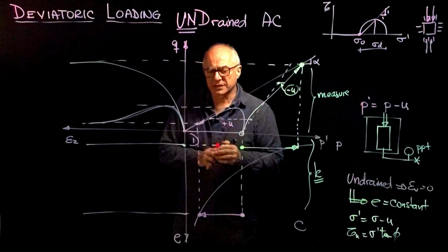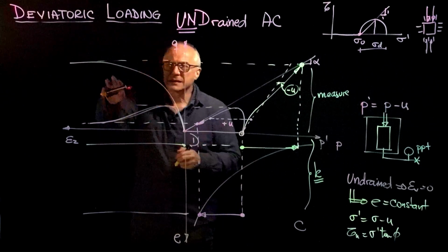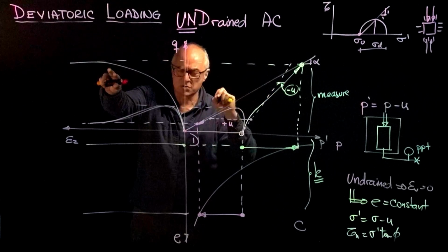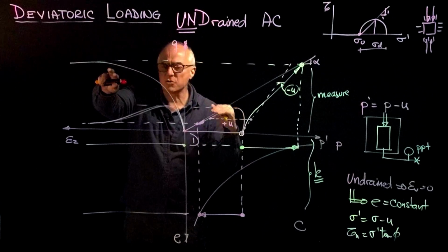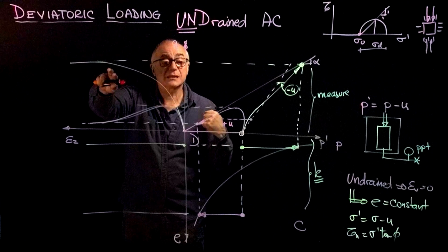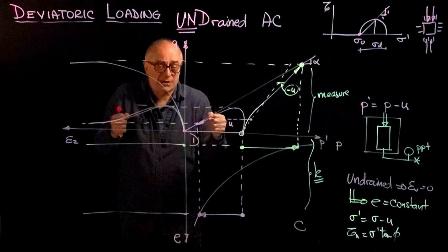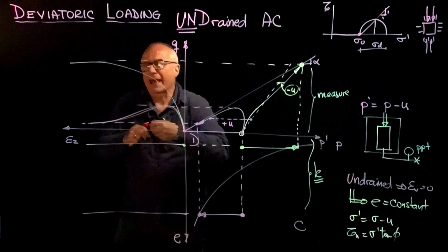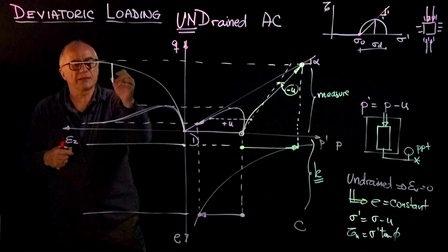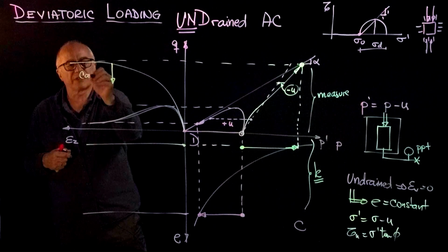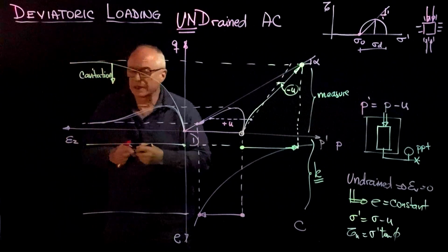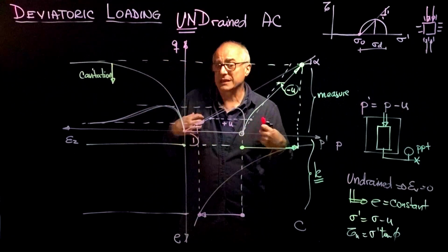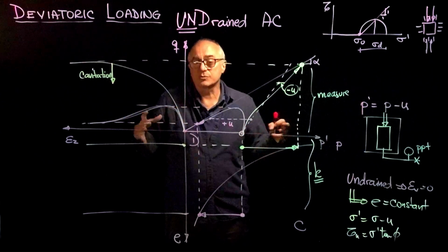The other observation that we want to make is that sometimes the negative pore pressure that we generate is so low that the pore pressure drops below 100 kPa. That means that the water goes into such a tension that it breaks down, bubbles form. And if that's the case, now the pore pressure vanishes, and you may see a drop in strength, and that drop in strength is because of cavitation. That happens when the sediments are truly dilative. In the laboratory, we can prevent cavitation by running the test with back pressure saturation.